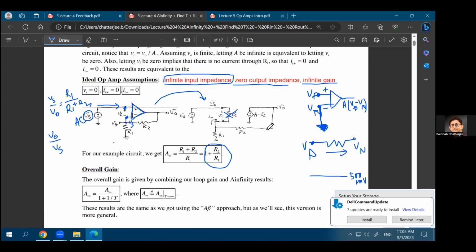That's it. So if you assume that to be correct, this point is Vs and this point is V0, you already know the voltage division ratio of Vs over V0. That is R1 divided by R1 plus R2, because this point is V0. I'll just draw it in a different way. So this point is V0. You have the R2 resistance after V0. Then you have this R1 resistance, which goes to the actual ground. And Vs is basically the midpoint of R1 and R2.